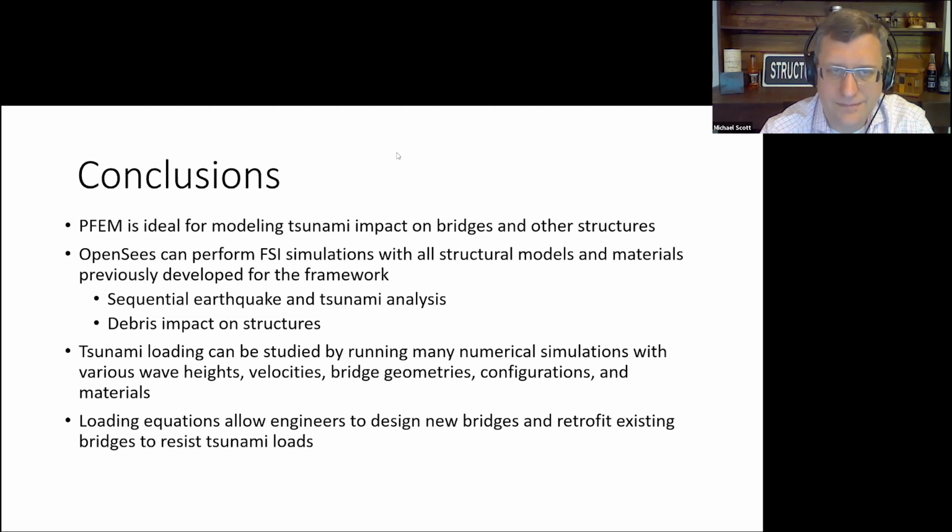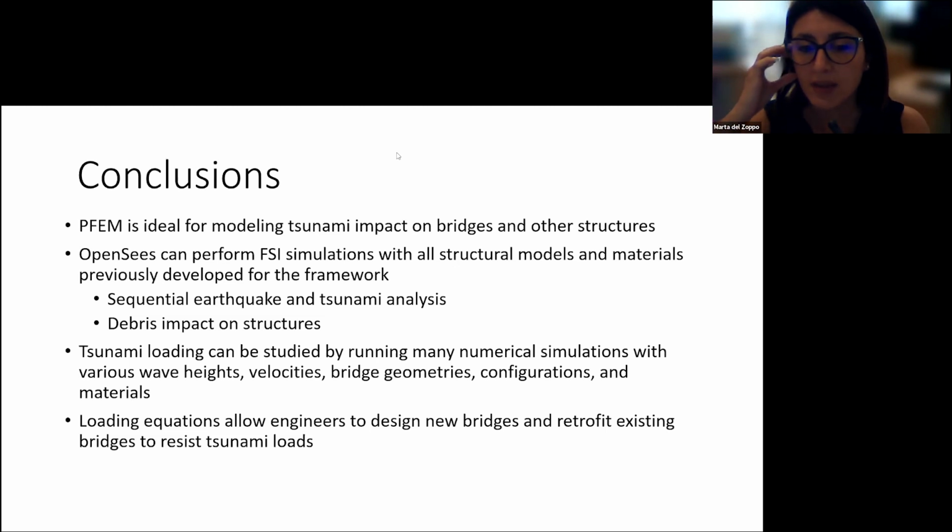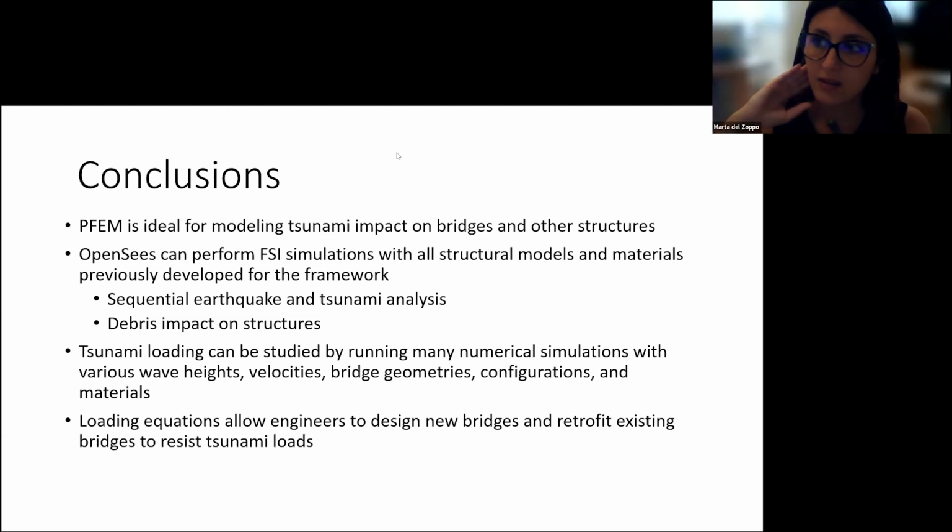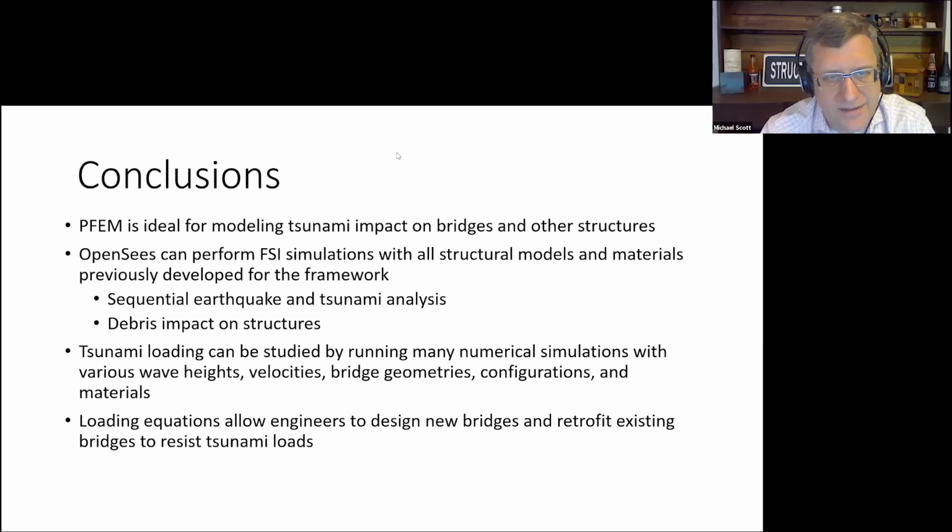So, okay, basically with this software, we can model the entire inundation. So we can simulate an inundation and see which are the solicitation, bending moments, and shear force in the structure during the entire loading. Yes. Okay. Yes. And this is feasible, the computational effort is not so heavy, we're talking about 2 hours or something.